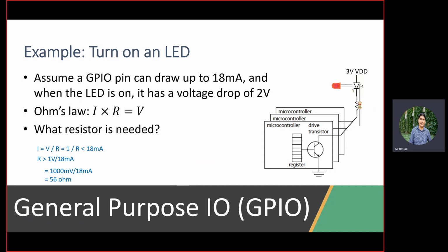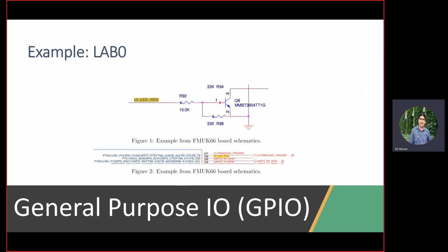This is probably, if anyone in high school had an Arduino for the very first time, usually they ask you to put an LED with a resistor and then a potentiometer, and then you keep switching the potentiometer to determine how the LED intensity is. That's one of the very simple experiments we teach for high school students. The reason this is happening is because by changing the resistor, you change simply the voltage drop across the resistor, and hence the intensity of the LED that is driven by the Arduino in that case.